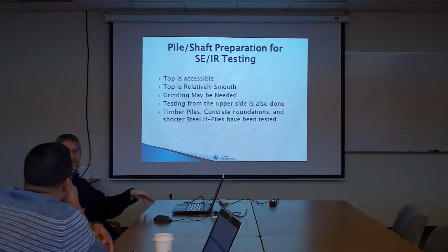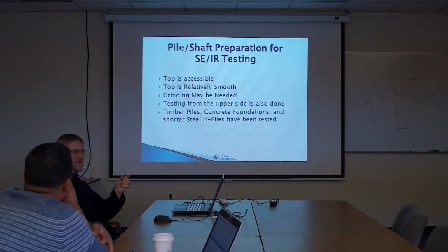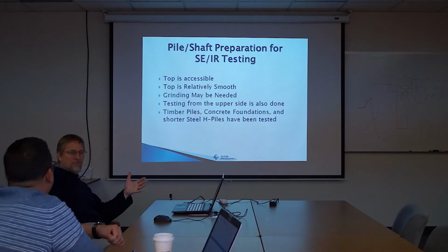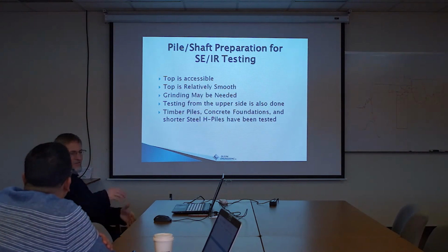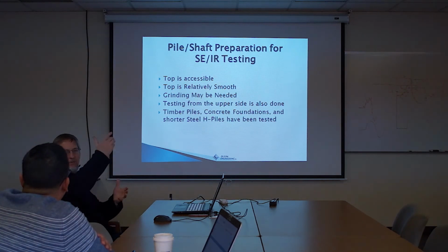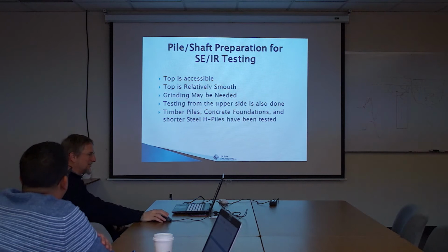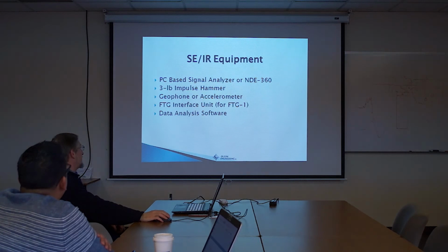It all dissipates into the soil from the sides of the H pile, because there's not enough meat in the pile to carry the wave energy down. So it dissipates, and by the time it echoes from the bottom and comes back up, the echo is just too small, and it just disappears. So these are the basic systems we use.